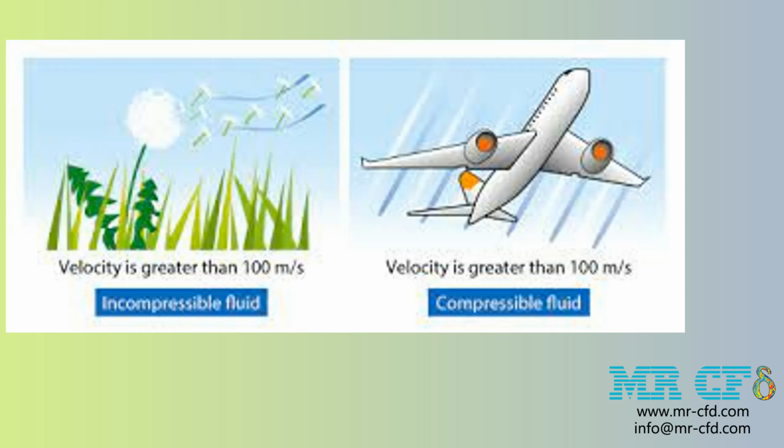Actually, a compressible flow is a branch of fluid mechanics that deals with flow having significant change in fluid density. While all flows are compressible, flows are usually treated as being incompressible when the Mach number, the ratio of the speed of the flow to the speed of sound, is smaller than 0.3, since the density change due to velocity is about 5% in that case.